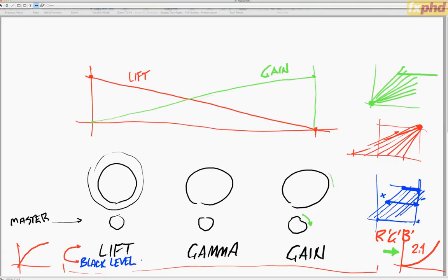Now, the third control is gamma. And what this is going to do is take your video signal level, I'll call it V, and raise it to some power, Greek symbol gamma. Now, you already know that there's gamma typically coming in, where the encoding gamma is something like 0.5, or if you talk to an HD engineer or a DIT, they may tell you, oh, I really like using 0.45, or most of my colleagues use 0.45, but I find I get punchier pictures by using 0.4. You'll have discussions like that among DOPs, camera operators. You know that there's gamma on the output end of the system. It's the display gamma, maybe 2.2, maybe 2.4, maybe 2.6.